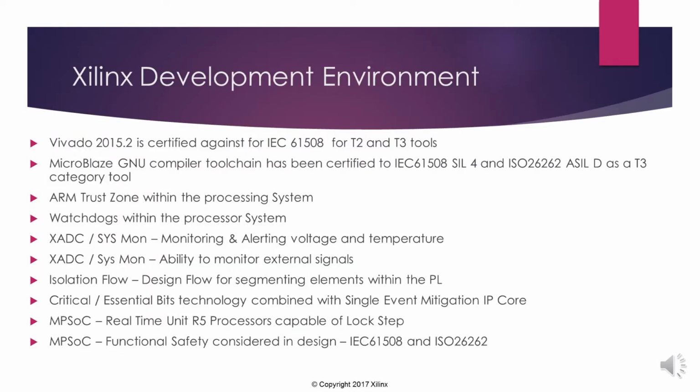So let's take a little bit of a look at a specific implementation now. And this is obviously based on my experience, it's based around particularly the Xilinx FPGA tool flow. So we're going to talk a little bit about the Xilinx slides now. So obviously the Xilinx development environment, Vivado 15.2, is certified for T2 and T3 tools. The GNU toolchain is actually certified up to SIL 4 or ASIL level D. And obviously there were other things that I've not mentioned much in this talk, because there was a Xilinx talk the day after and I didn't want to cover the same ground.